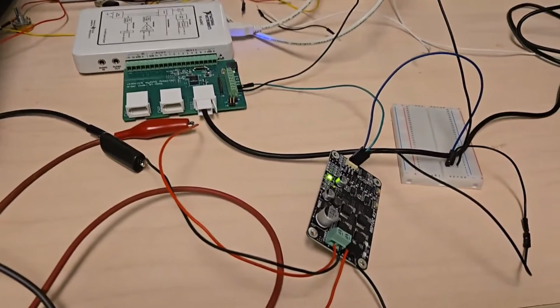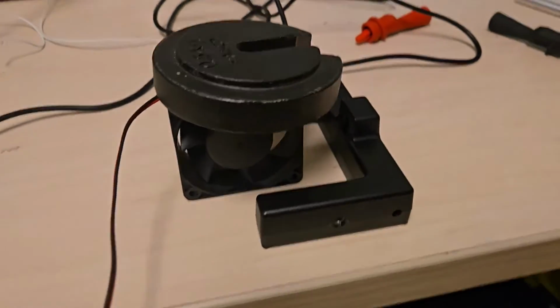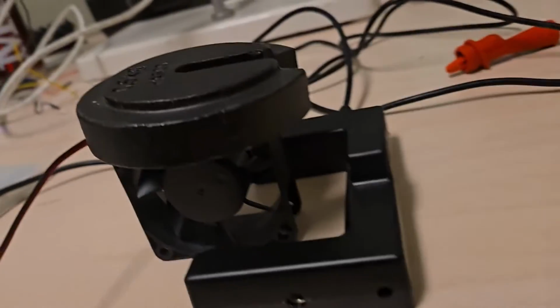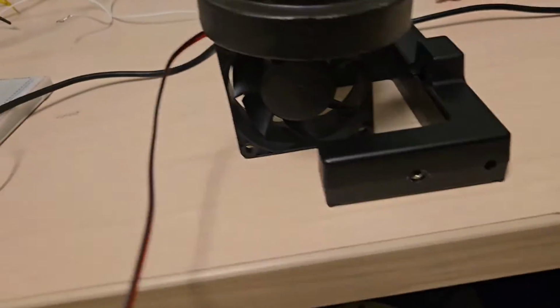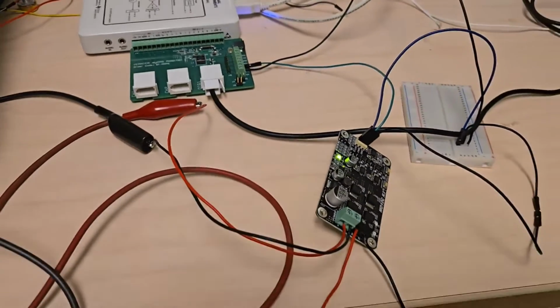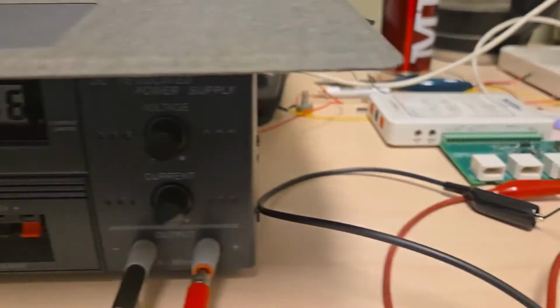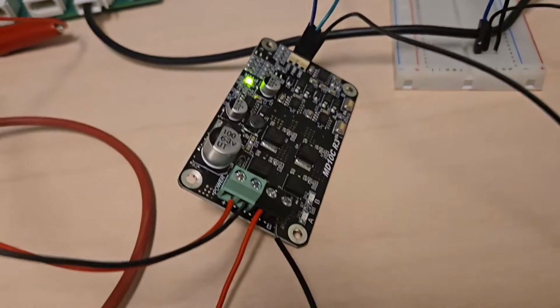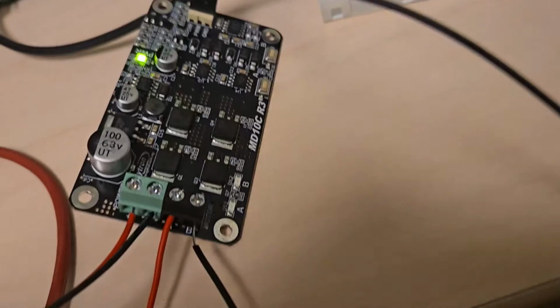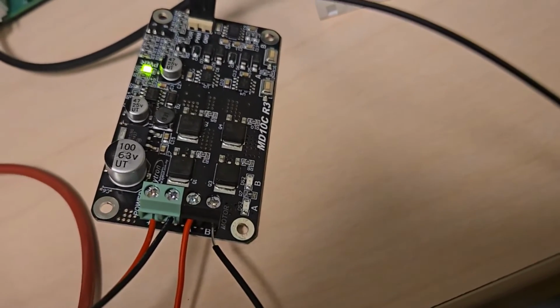All right, everyone, we are back, and now we're going to do our fan control lab with our Vernier Photogate, calculating the RPM, but now in a controlled manner. So, power supply, 12 volts, approximately. That feeds directly into our old friend, the power supply on our motor controller. A and B go directly into our fan.